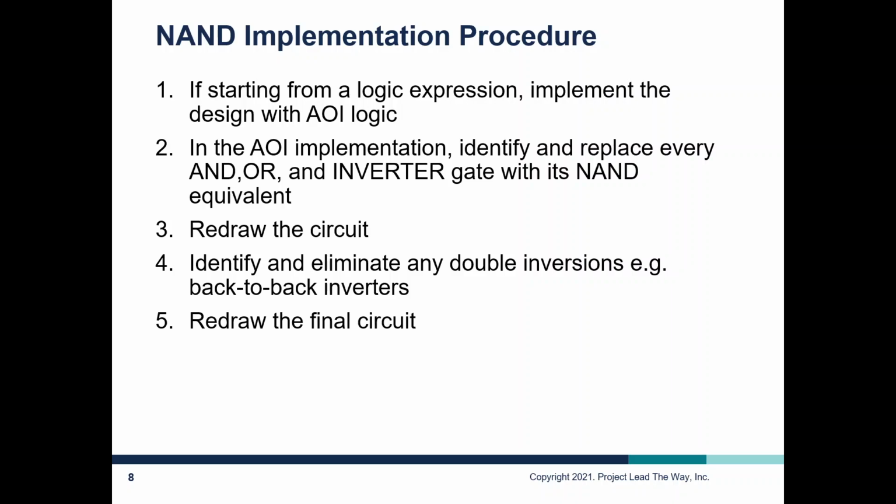We then redraw that circuit. We identify and eliminate any double inversions, in other words, back-to-back inverters, and then we redraw the final circuit. Let's go ahead and walk through that.